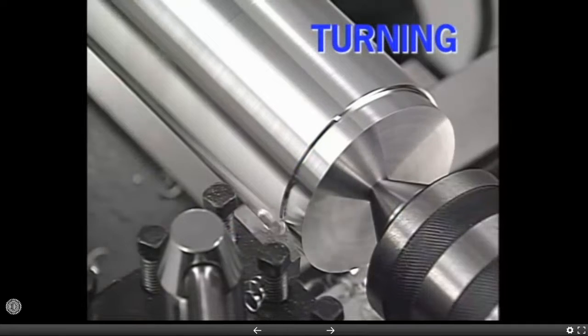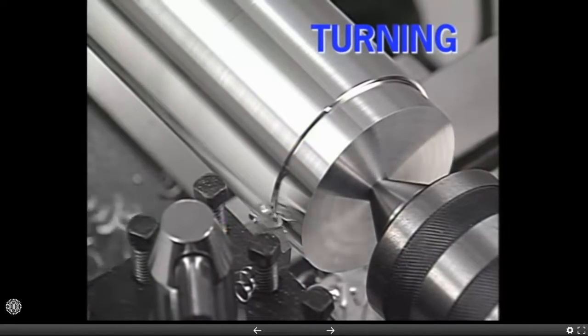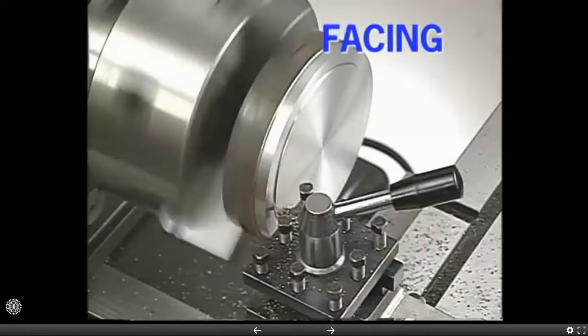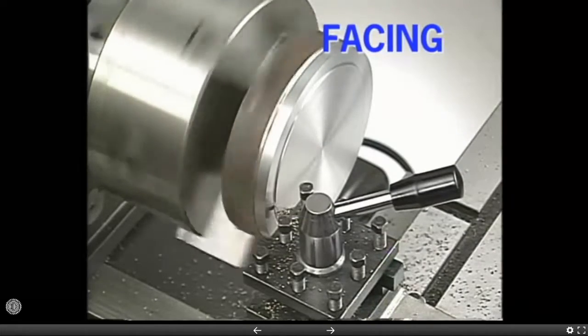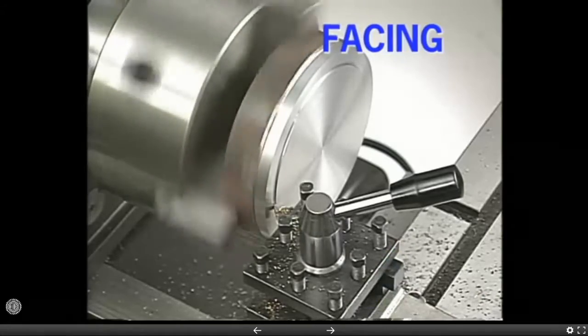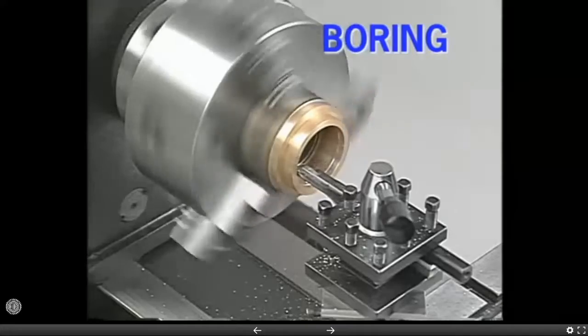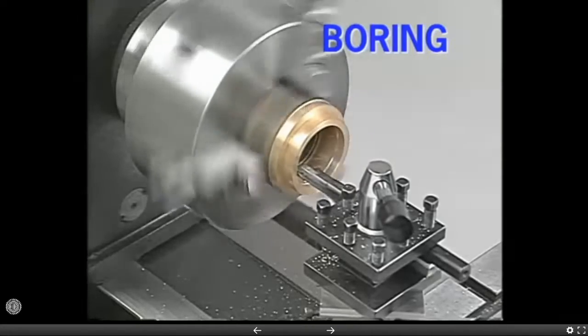In a turning cut, the tool is moved parallel to the lathe axis to remove material from the outside diameter of the workpiece. In a facing cut, the tool moves at right angles to the lathe axis, removing material on the face or end of a part. A boring cut removes material from the inside diameter of a workpiece.